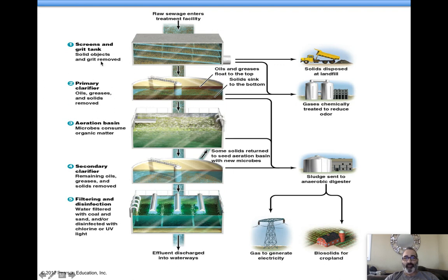This is primary treatment. Then you aerate it, which means you pump air through it and you have microbes and bacteria pumping through it. Why air? Because the bacteria likes oxygen, and then it can decompose it and start breaking it down in secondary treatment, where it's then filtered and disinfected with UV filters. It's filtered through coal, chlorine, you name it. That's what they'll use to kill the microorganisms at the very end. And they pump it out, basically.